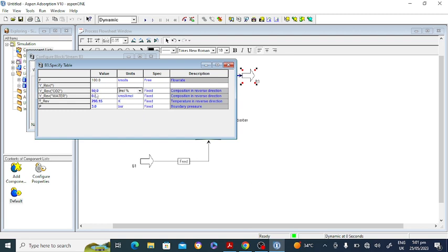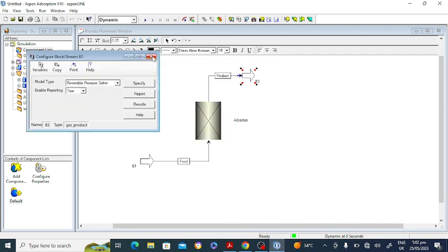The carbon dioxide mole fraction in the feed was 40, and I am assuming 20 in the product, because some carbon dioxide is adsorbed on the adsorbent particle. The mole percent of the water vapor I am assuming is 30. The temperature is constant, this is an isothermal process, and the pressure changes. I am assuming 3. Click on OK, and click on OK.